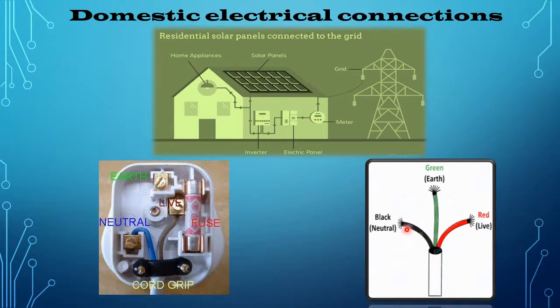At the meter board, these wires pass into an electric meter through the main fuse. The main switch, live wire and the neutral wire are in connection to the line wires in our home. These wires then supply electricity to the separate electric circuits within the house. The third wire is called the earth wire and is of yellow or green color.